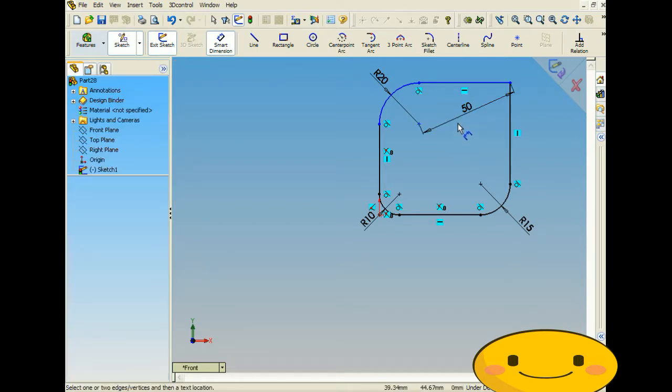So the advantage of doing it in here is that you're able to adjust everything beforehand, just make one extrude, and you're done, rather than creating the extrude, doing the fillets on the feature, and then making a cut or extrude, whatever else you have to do. So that's the advantage of this. It's a lot easier, it lets you manipulate the sketch a lot more, and the whole part altogether, and saves you some time. And that concludes our tutorial on how to use the Fillet Sketch feature within Solidworks.